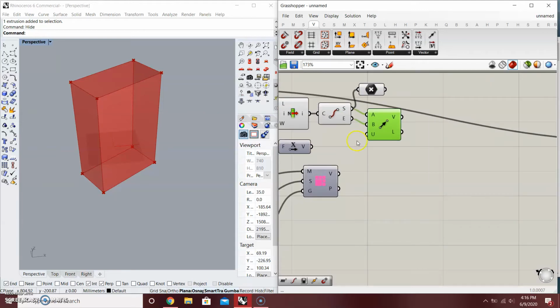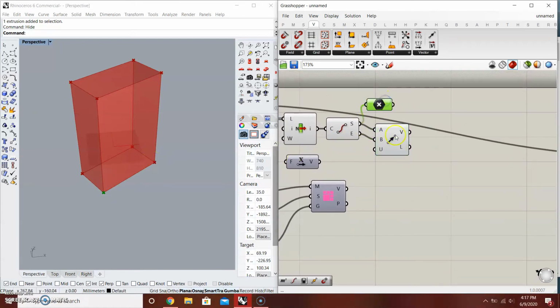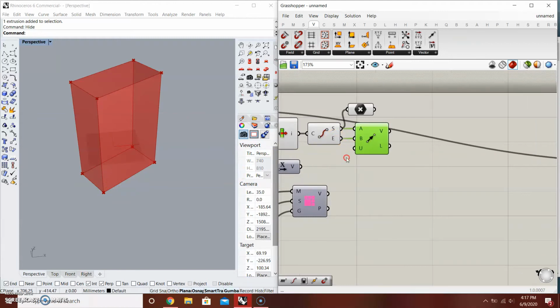If not, there's going to be a lot of problems, because for example, you have the starting point here and the point of rotation there. The angle will not match up. So make sure that you have the starting point and the center point of rotation the same, or you have the end point and the center of the rotation the same. Basically, you want to have it consistent.